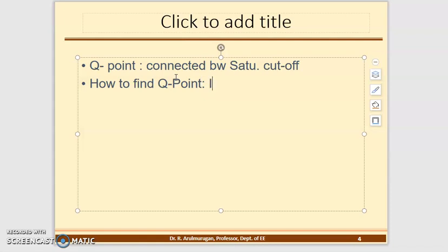One is the collector current, which is equal to gain multiplied by the base current, the input current, multiplied by beta, the gain. You use the input to find it, and then you use one more formula for VCC. You need VCC and IC, and if you have these, then you can find the Q point. That's all.